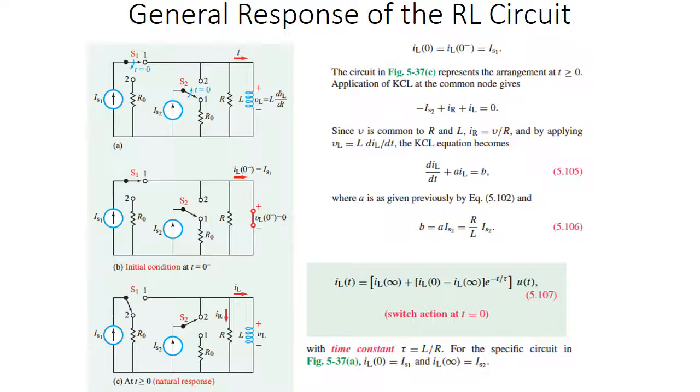So all of that current is going to go through that line and not through the resistor to the left of it. Everything goes through the inductor because, again, it's just a metal wire, so you're going to be able to short through that piece of the circuit. So that's why we have our V_L of 0 minus equals 0. There's no voltage drop, and essentially you have a short circuit right there.